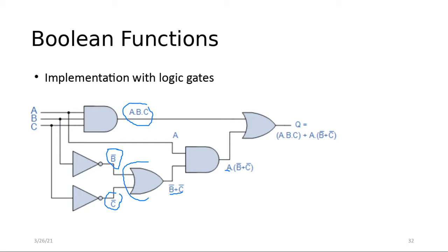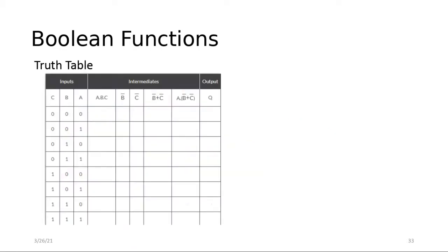And we have the last one. The last one is an OR gate, and there are 2 inputs. One input is A and B and C. The other one is A, parenthesis, NOT B or NOT C. So just OR these 2 expressions, and you got the answer. So let's do the truth table of them. We have an AND gate. In an AND gate, 0 is effective.